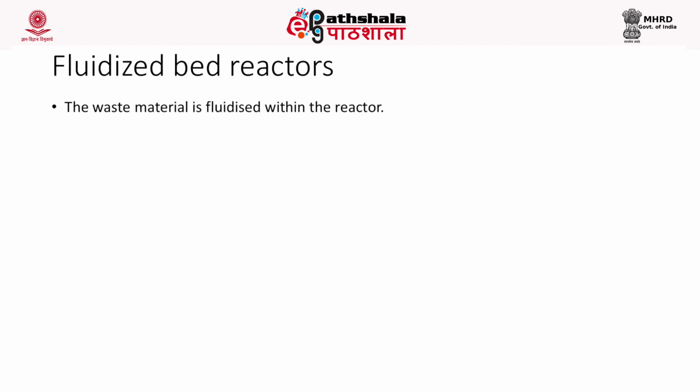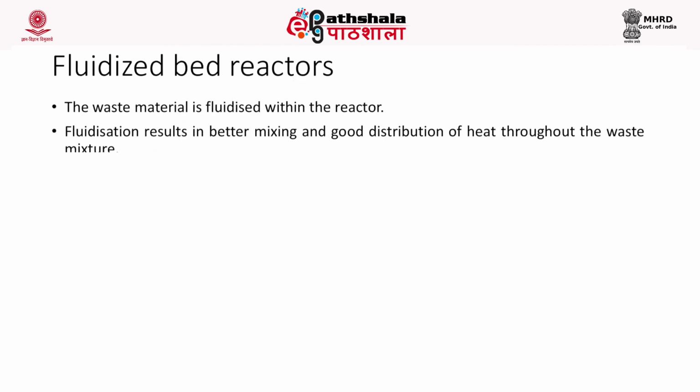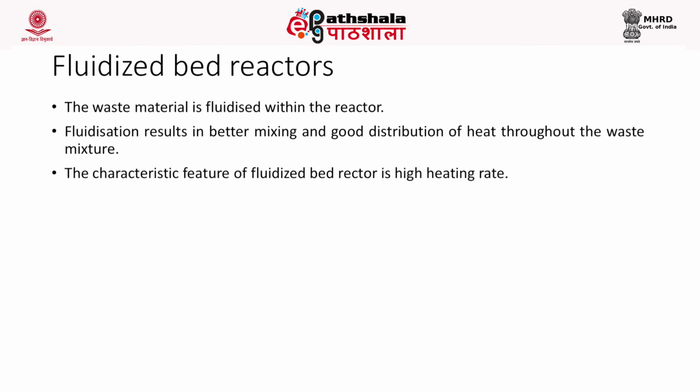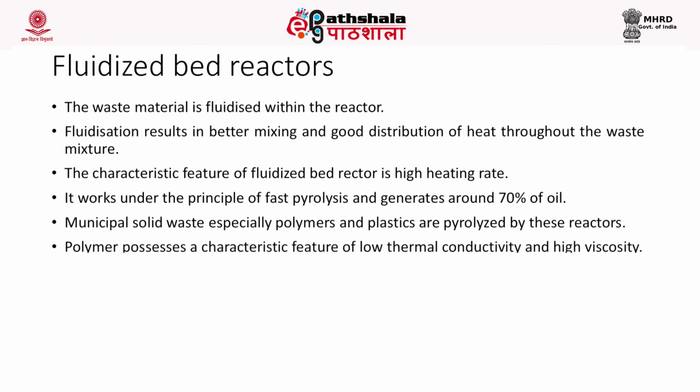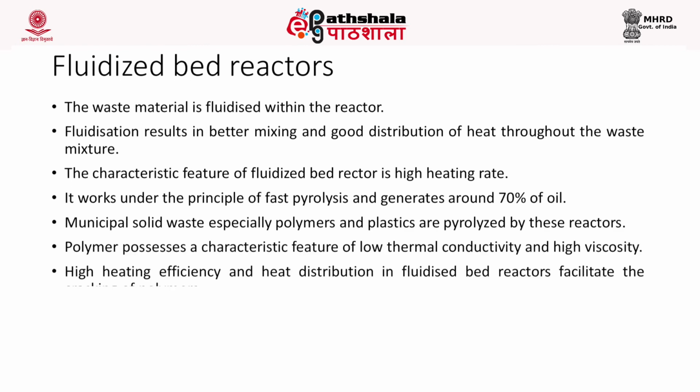The third type of reactor is a fluidized bed reactor, where the waste material is generally fluidized within the pyrolysis unit. Fluidization generally results in mixing and good distribution of heat throughout the waste. The characteristic feature of fluidized bed is high heating rate. It works under the principle of flash pyrolysis and it generates around 70% of oil. Municipal solid waste, especially the polymers and plastics, are pyrolyzed using the fluidized bed reactors. Polymers possess a characteristic feature of low thermal conductivity and high viscosity.